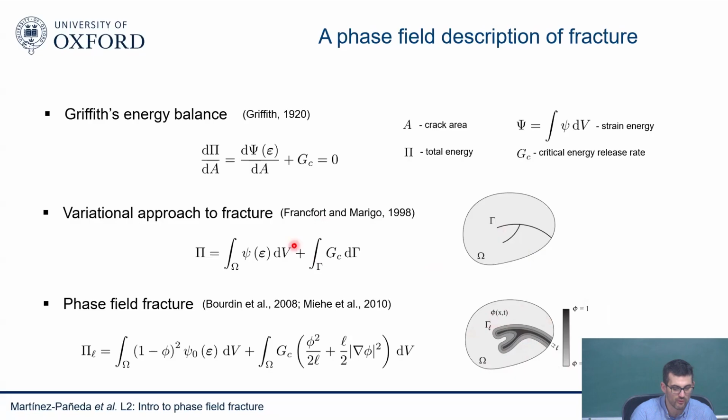So then we can regularize this functional. This surface integral becomes a volume integral. And then, using finite element methods, we can easily minimize this functional. So we can predict the evolution of cracks as an exchange between fracture and stored energy, elastic strain energy and fracture energy.